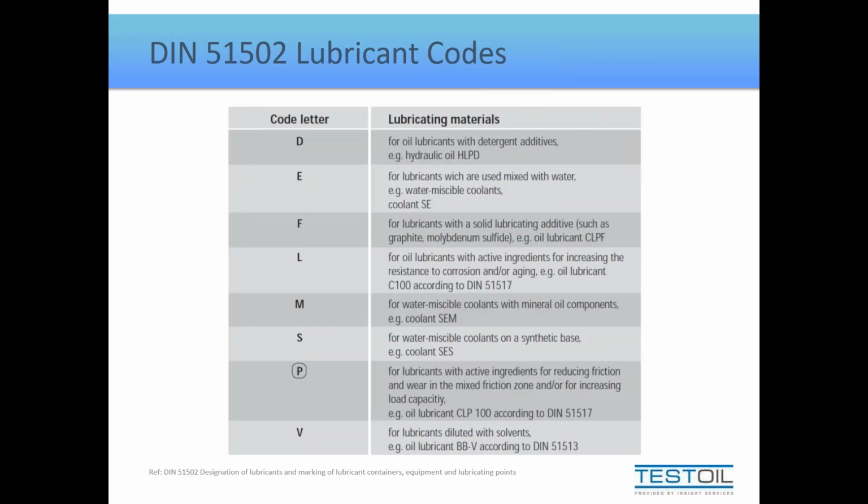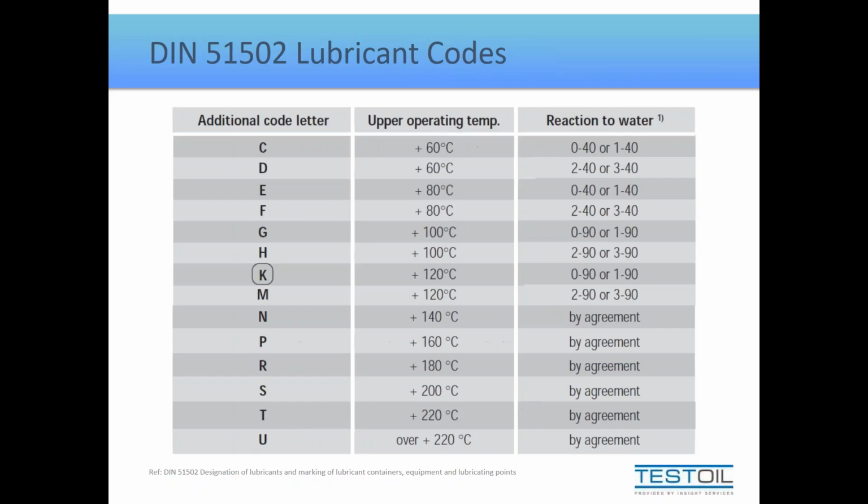So I've broken down the first K on this slide. You can see what P stands for. On this slide, basically it just describes the type of base materials going into the grease, what kind of lubricant we're using, and may refer to some of the additives. The 2 obviously was the NLGI 2. The next K, like I said, had everything to do with how well it reacts with water. So this gives us a reaction and an upper operating temperature just broadly. And like I said, the last number refers to minimum service temperatures.